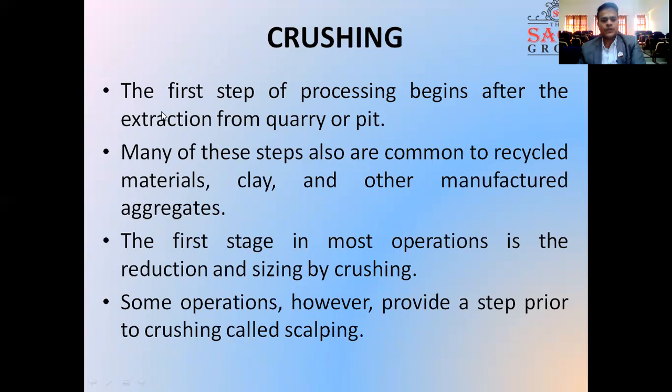So, crushing, the first step of processing after the extraction of material from the quarry pit, is called crushing. It is common with recycled aggregate, clay, and other manufactured aggregate. The first stage in most operations is the reduction and sizing by crushing. That means the material which is collected from the quarrying site needs to be crushed or reduced in size so that it can be converted into a usable form.